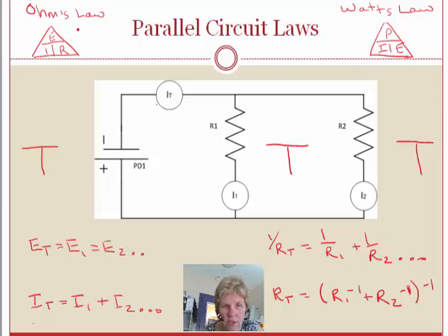Have a look. On the top of the slide, on the left-hand side, we see Ohm's law, E equals I times R, and on the right-hand side, we see Watt's law, P equals I times E. We use those with series circuits, and they'll also work with the parallel circuits. Towards the bottom of the slide, though, are rules that only apply to the parallel part of the circuit.